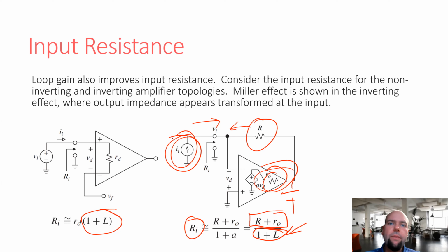But what it means is the output capacitance of an amplifier circuit can show up at the input of the amplifier. This has really big implications for cascaded amplifiers. A lot of times what we want to do is say, let's do a gain of 10 amplifier followed by a gain of 10 followed by a gain of 10. And one issue with Miller capacitance is the input to this cascaded set of amplifiers will still be seeing the capacitance of the very output. So the features of the output of this cascaded amplifier network will still show up at the input, which can have undesirable consequences for your circuit.